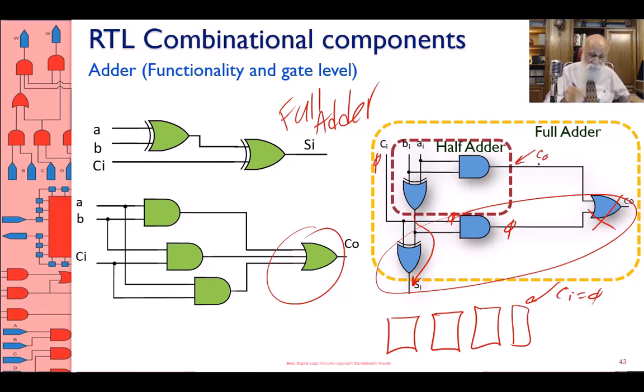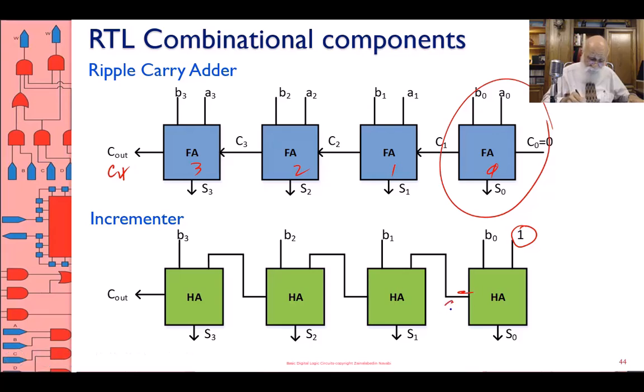This is the carry out for the half adder, and the half adder carry out becomes the input into the next one, and therefore this is a simple incrementer. There is no point in using a complete adder if your only task is incrementing. This incrementer has some good property. Look, if this one is 0, this incrementer doesn't increment. So it's really an incrementer with enable.